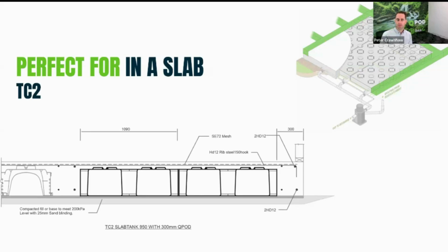So that's really showing how it would tie in with a typical TC2 raft floor, where you've got your ribs at 1200 centres. Those ribs would be regenerated in a 300 rib at 3.3 span, if you follow that. So it recreates your shear further out. And that's how it keeps it really simple in terms of keeping these tanks together and with installation, and then fitting them into garage spaces in the slab.